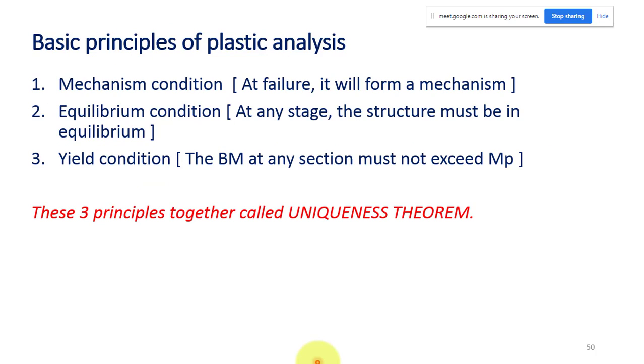Similarly, we have three principles, or three conditions, for your plastic analysis: the mechanism condition, the equilibrium condition, and the yield condition. The equilibrium condition is common in both elastic as well as plastic analysis. So whatever your analysis is, equilibrium is a mandatory condition. It has to satisfy equilibrium. Equilibrium means at any stage, for your structure, the algebraic sum of all the forces and moments should be zero.